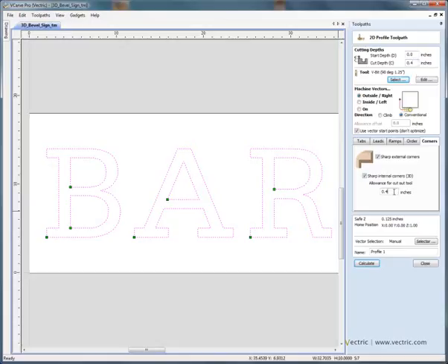If we were using a different angle cutter, say for example a 100-degree or a 110-degree V-bit to add the chamfer, then the depth and the offset would be different. But you'll see in a moment that we need to use this value, so it's worth making a note that the allowance offset needs to be 0.4 of an inch. Let's give this toolpath a meaningful name. So I'm going to call it chamfer and calculate.